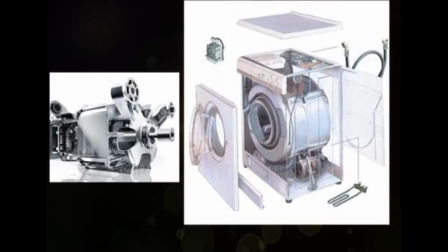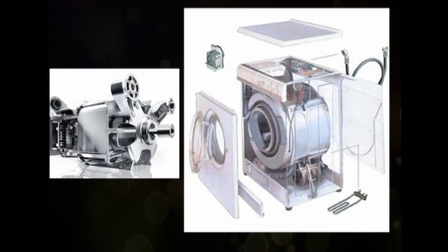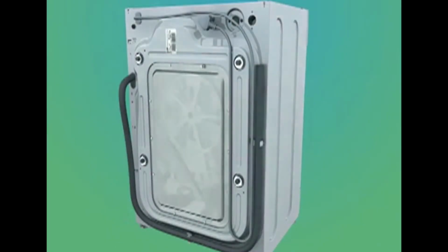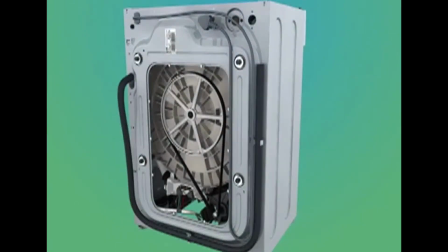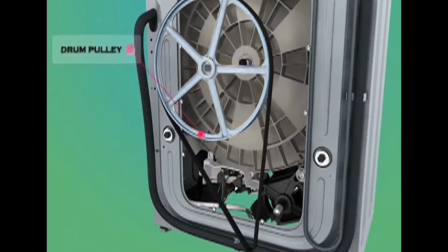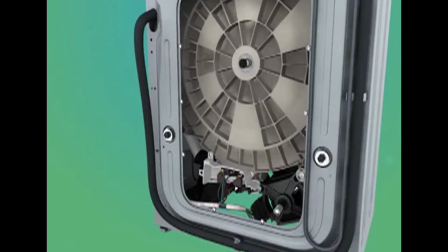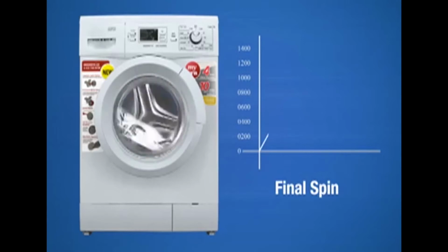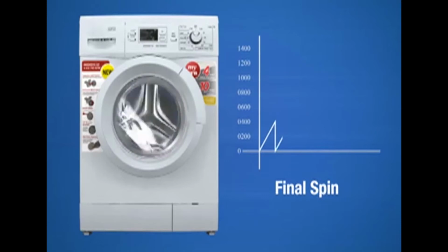The washing machine operates by a motor, which is connected to the agitator through a unit called a transmission. The motor and transmission are near the bottom of the machine, while the agitator extends up through the middle of the machine. The transmission changes the speed and direction of the agitator. In one direction, agitate, the transmission changes the rotation of the agitator and moves the inside tub, with small holes in it, in a back and forth motion.